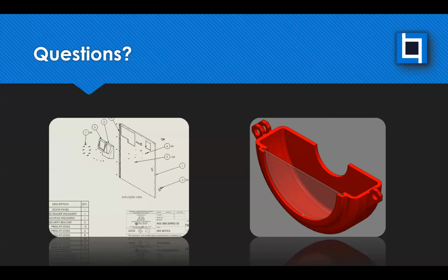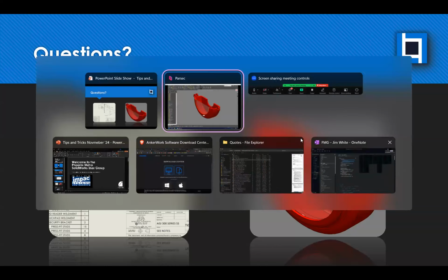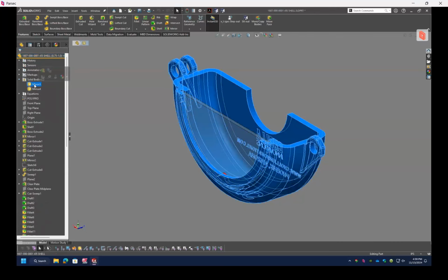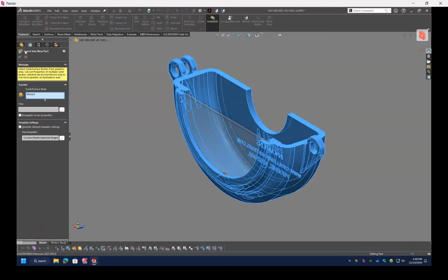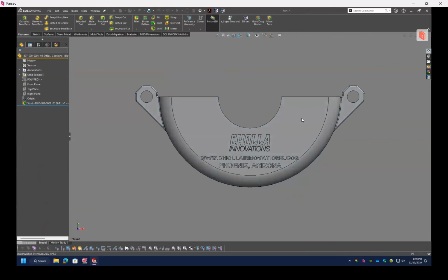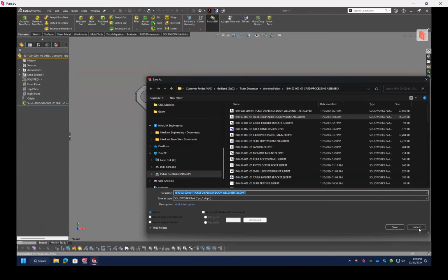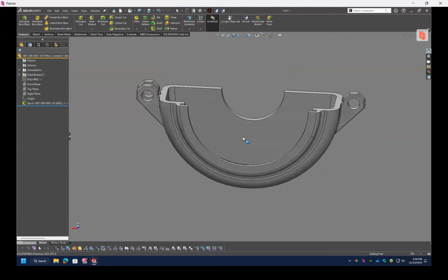You are able to export that as two parts, as an assembly if you want, right? Yeah, totally. Actually, let me show you that real quick. I had intended to show you that and I forgot, so I appreciate you bringing that up. There's a couple different ways to break it out. You can do an insert into new part. Essentially you can manually break it out as its own part. What you end up with is what some would call a master model. I'm just going to hit cancel on that, but you end up with a master model.